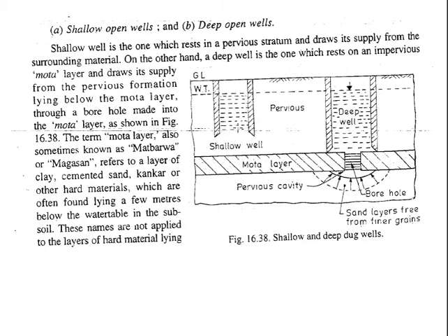And one more statement is that you should not conclude that if it is a shallow well, then its depth will always be less in comparison to the deep well. It's not like that. There are certain cases in which the shallow well depths are quite large in comparison to the deep well. So it really depends upon when these types of wells encounter this impervious layer.